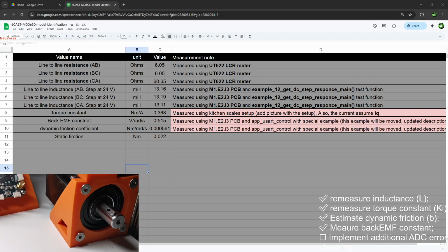So I guess at low voltage you have huge current. This motor does have a high current. If I were to short circuit it, it only has 6 ohms resistance. So if I were to put 48 volts at 6 ohms, I would get like 8 amps, and at 8 amps it will burn out in like 3 minutes, I guess. And at 220 volts, if you don't control it in any way, you will just blow up the motor in seconds. It will just poof, and the motor is gone. The motor is completely gone.